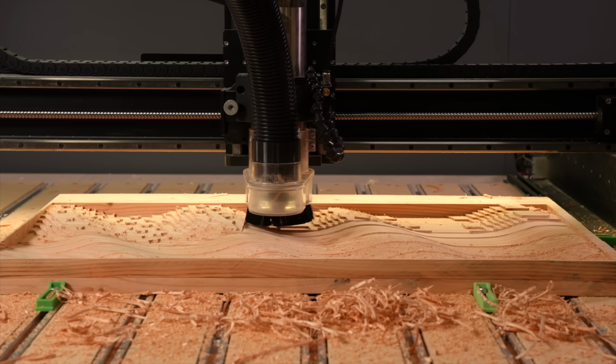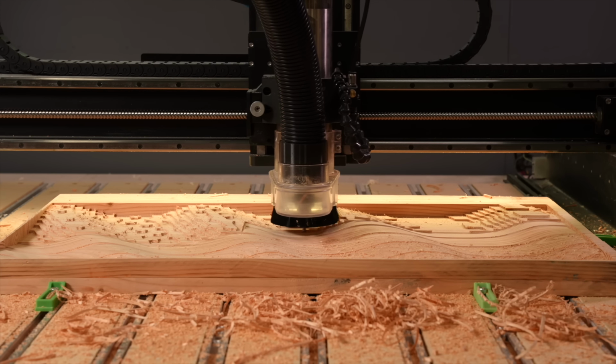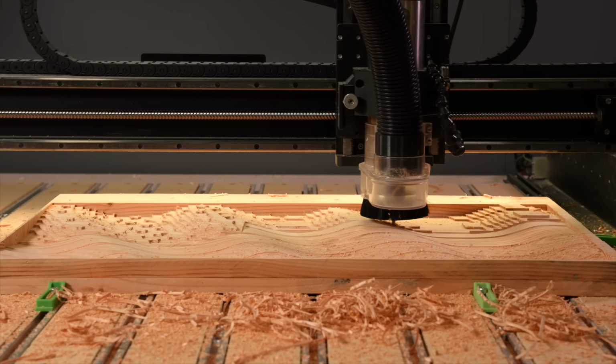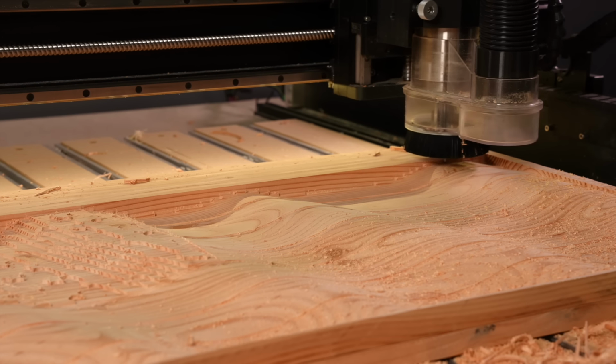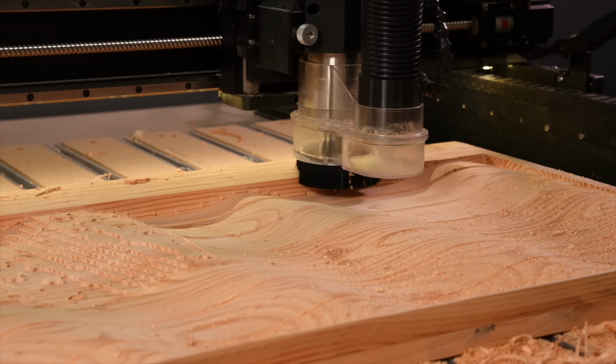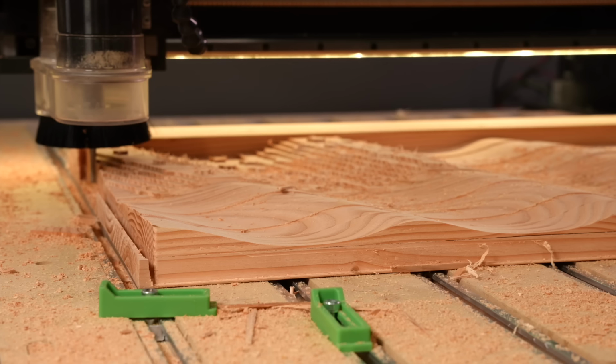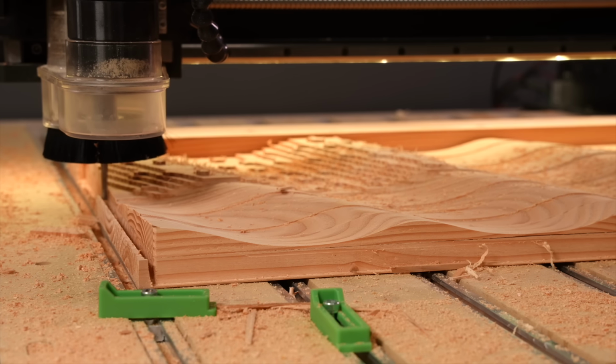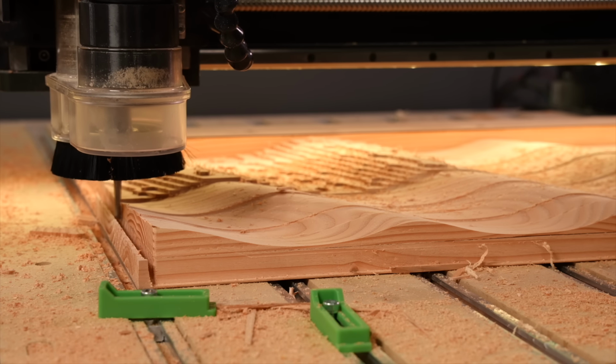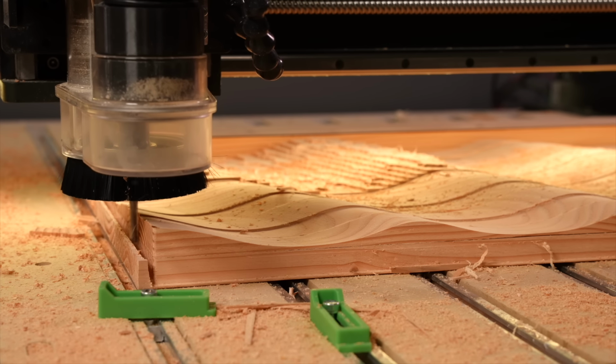I'm just taking advantage of the fact that this toolpath uses the same end mill as the roughing toolpath. The machine won't need to stop and ask for a tool change, which means I can let it run unattended while I do something else in the shop. And the final act of this 1/4" end mill will be to cut out the profile of the flag. I'll need to remove the clamps for this step.